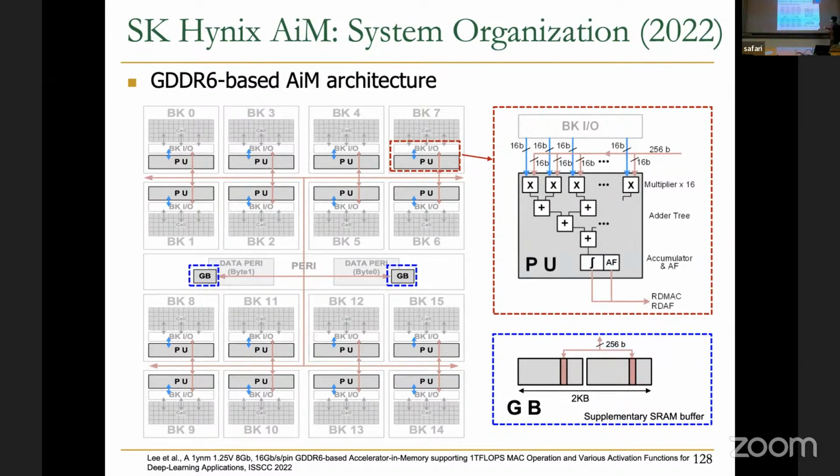There is something I like from this proposal: they also figure out a way of evaluating or executing activation functions in a fast and efficient way, and they do it in a similar way as we did with the AppMem architecture for sigmoid that I just mentioned a few slides ago. It is by using a lookup table in some of these DRAM cells, in some of these rows in each memory bank, and then they also have an interpolation unit in order to be more precise in the calculation of the activation function.